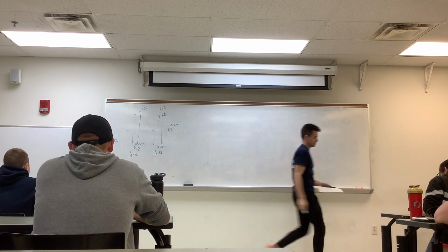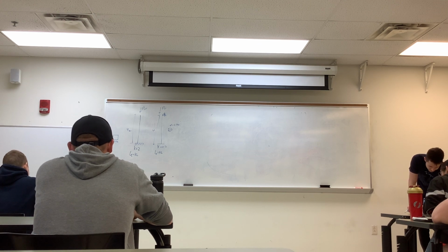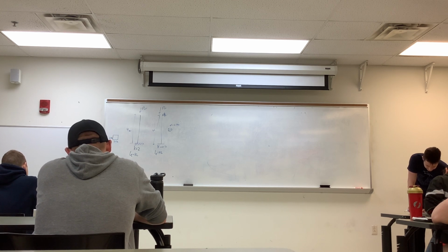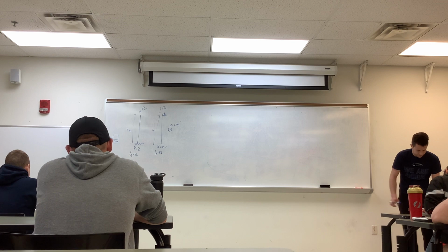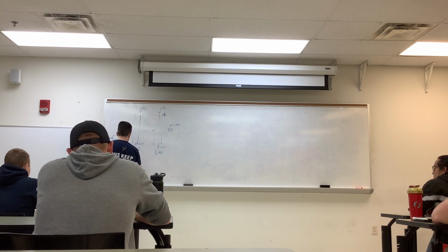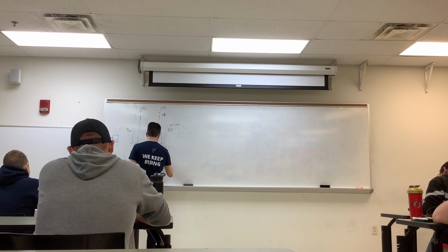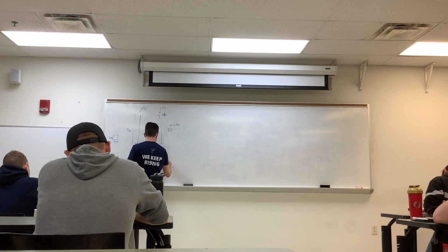This is where I'm actually going to need your calculator since I came up with these. So our effective length for the fixed free one is just 2 times 4, which is 8, and then the effective length for the fixed pinned one is 4 times 0.7, which is 2.8. So we have length effective equals 8, and length effective equals 2.8. These are both in meters.